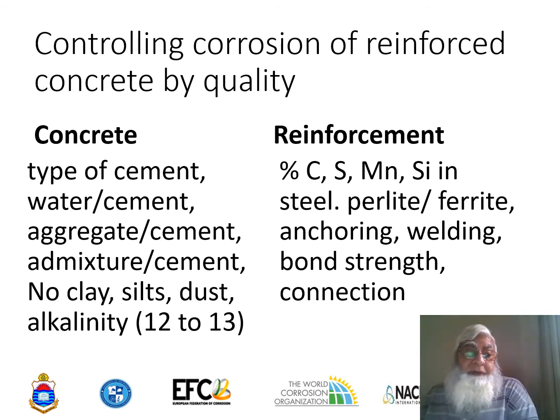But the only important thing is that the concrete and all the admixtures, aggregates, and cement should be free of any loose clay, silts, and dust. And alkalinity is a very important factor that needs to be somewhere between 12 to 13 in the concrete pores so that the concrete remains alkaline and can become protective for the reinforcement, mainly for the carbon steel.